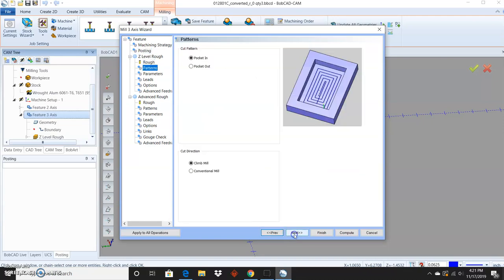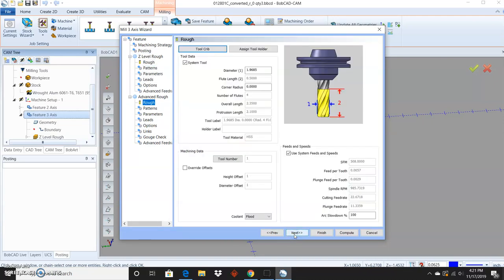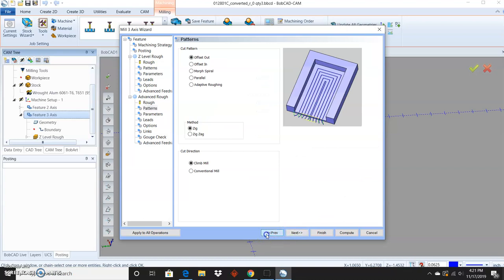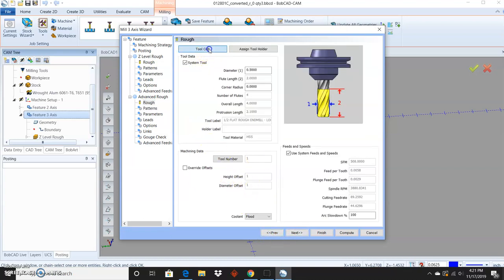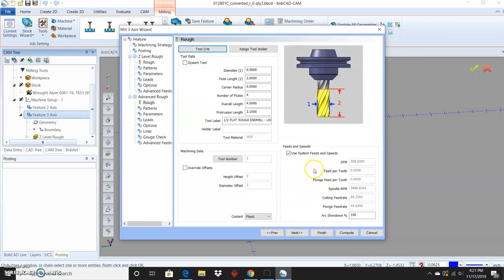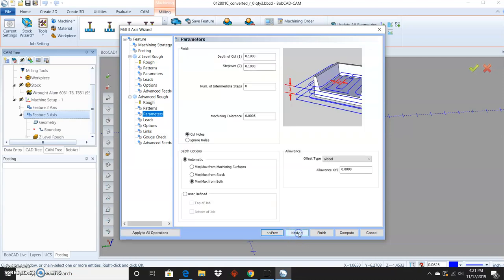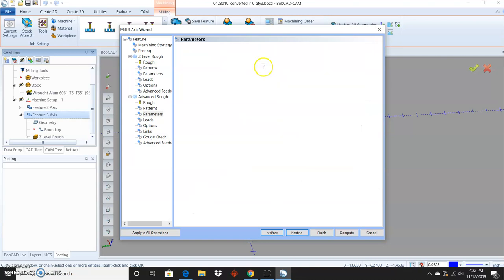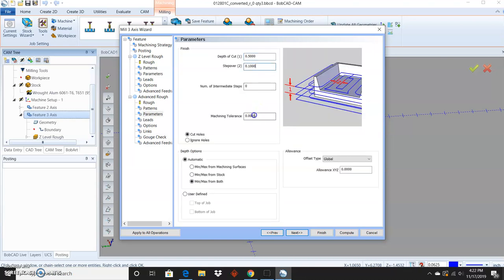Now this is kind of adaptable to just about any part to start out with. I want to use a 1/2-inch cutter. It's going to automatically make that. Hold on a minute. It didn't actually automatically make that tool one because I didn't have automatic tool numbers selected. So I'll make that tool 2 myself. Take the speeds and feeds. Actually, for depth of cut here, we can say 0.5 because we know we're not taking much.